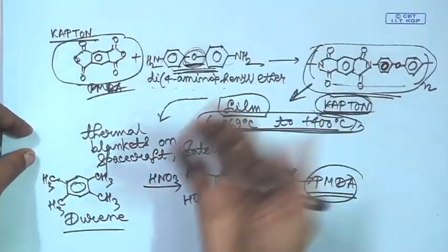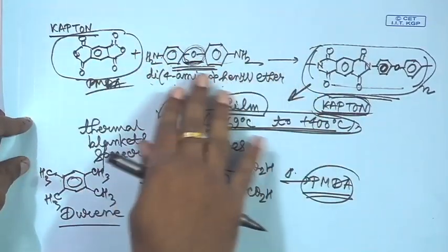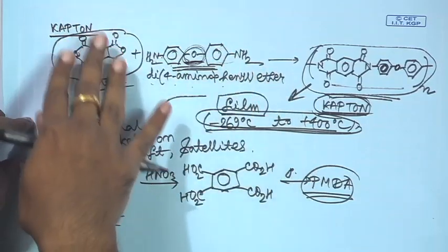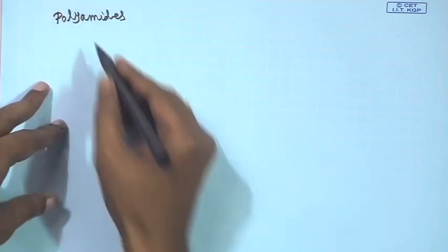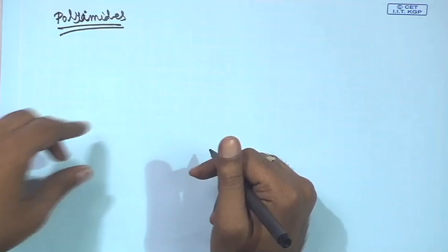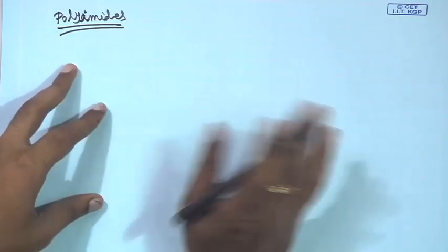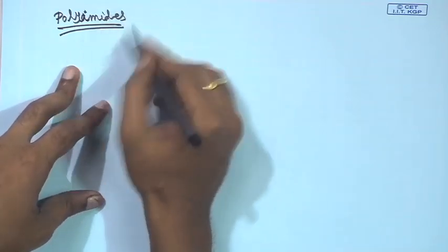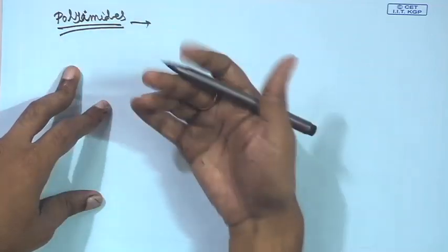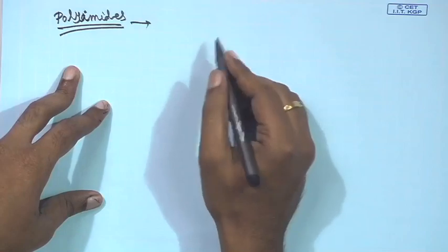I am talking about just a diamine which does not have any other linkage, say benzene ring NH2 NH2, reacting with a dianhydride, and so on. In those situations, although you can go through polyamic acid, the applications are quite limited because they are infusible, they cannot be molded by conventional thermoplastic techniques.